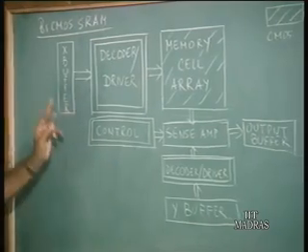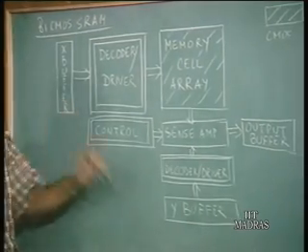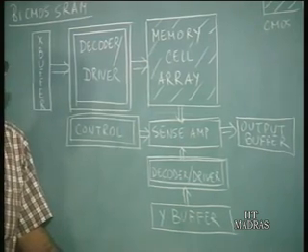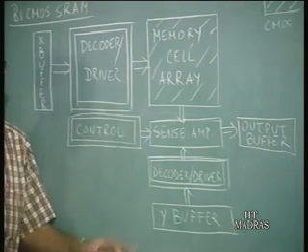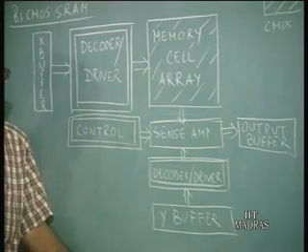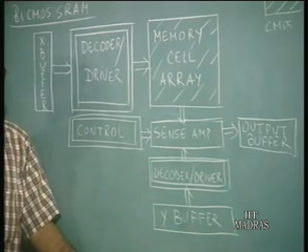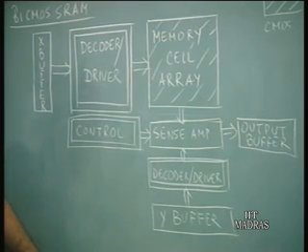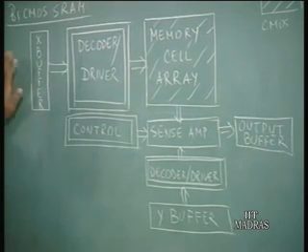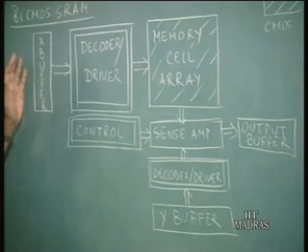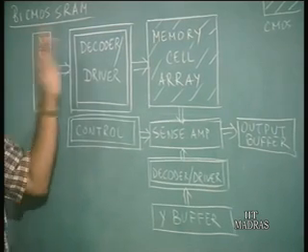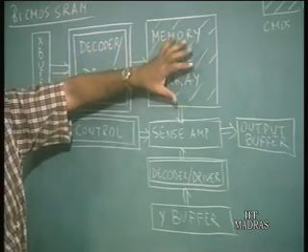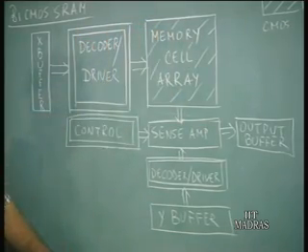Now, the buffers here are shown as bipolar because many of these BiCMOS memories have ECL type of inputs, which means the voltage levels are the same as for an ECL, that is, you have negative voltages as in an ECL. This must be converted to the levels which are understood by a CMOS circuit, because the memory cell is basically CMOS.